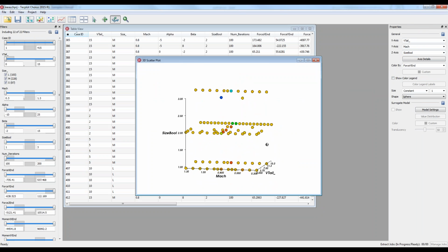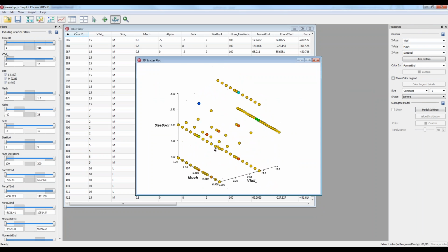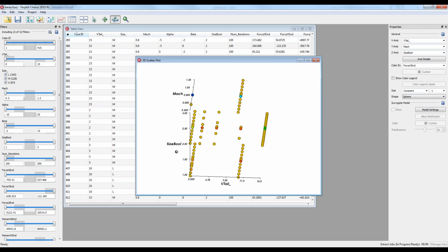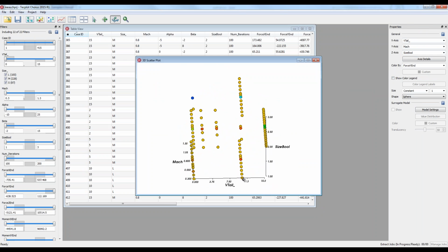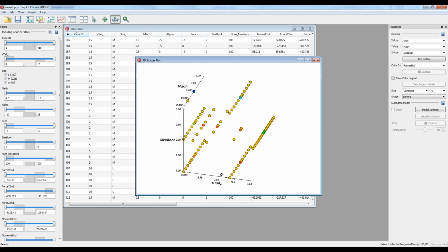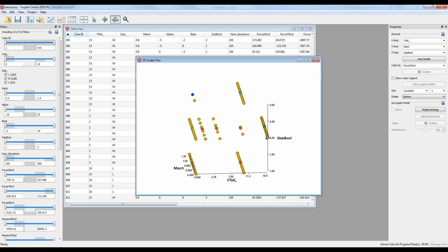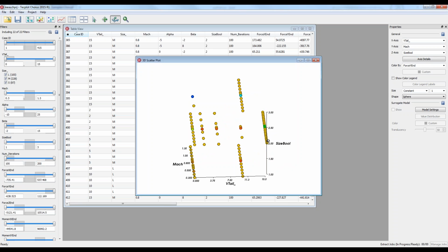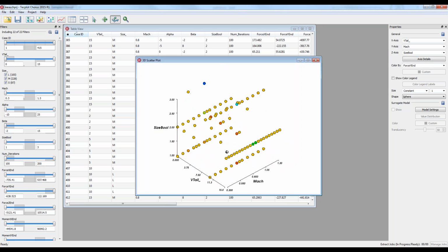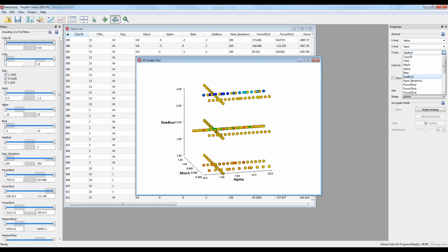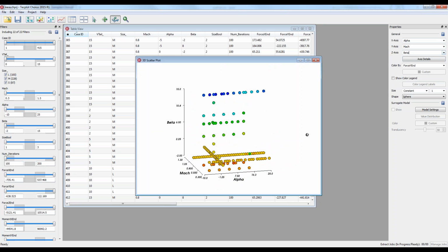You can see that we ran Mach sweeps on some of them, but not all of them, and that we ran at 0, and I think this is 10 degrees for the angle of the wing. We ran several of those. And under the medium, we ran one with a 15-degree sweep angle, or rear wing angle. So this is part of our design space. We could also look at Mach, alpha, and beta to just look at our initial condition space.